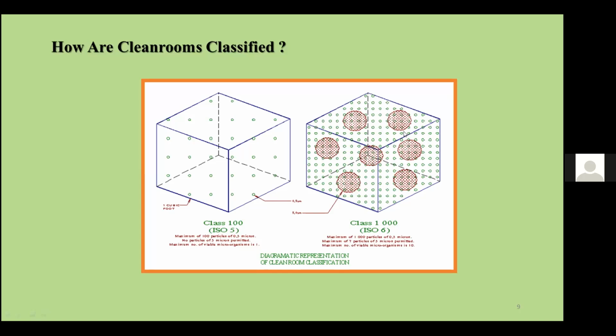Only for that case is a class 100 clean room needed. Otherwise, fabrication instruments or some production lines can be kept in a class 1000 clean room. Only wafer fabrication is done in class 100.